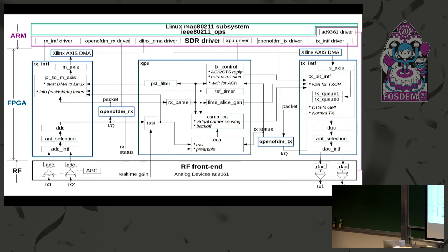Meanwhile, Linux will tell you, for this packet, you should try this MCS for how many times, try that MCS for how many times. The FPGA needs to do that. Linux waits for your result. So wait for the ACK, right? When you send the packet, your FPGA needs to wait for the ACK. Otherwise, you cannot tell Linux whether this transmission is successful or not. This is the TX path, which does the reverse processing of the RX.